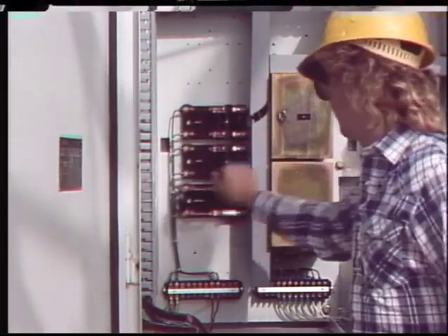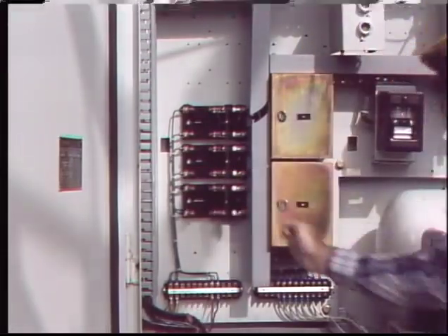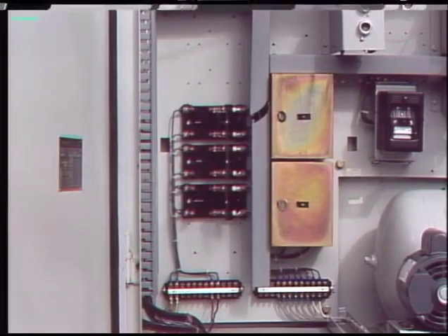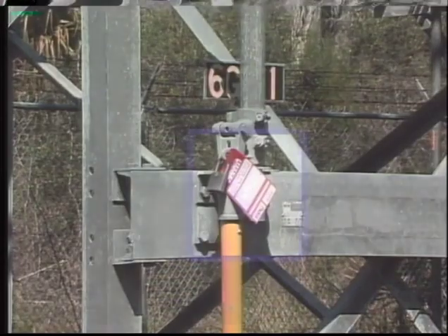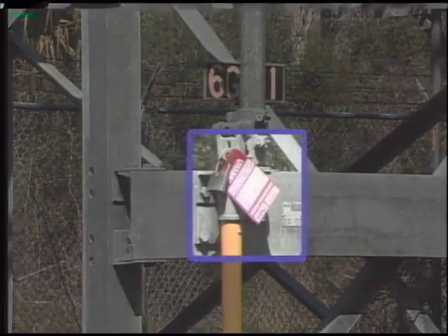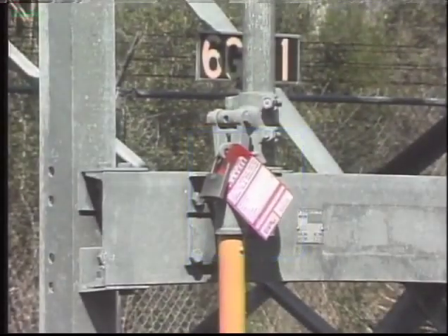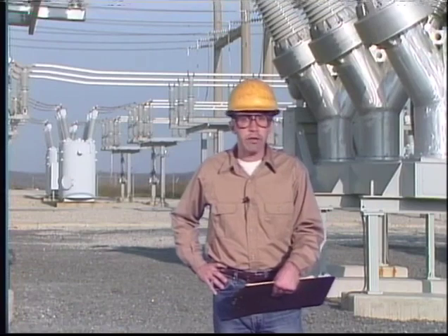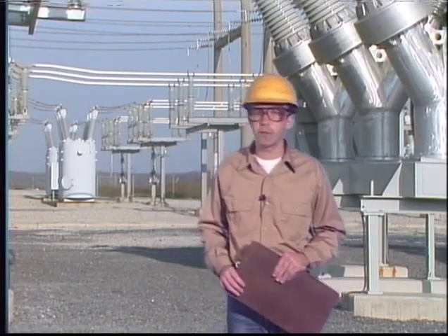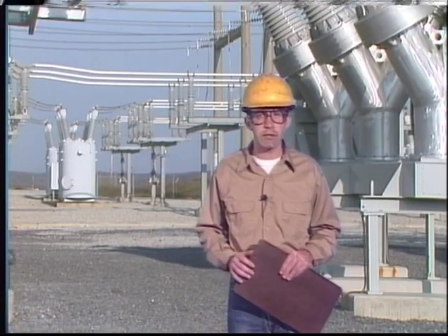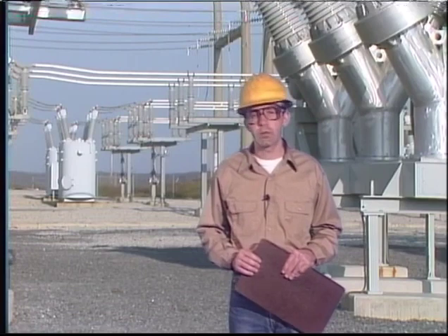Control circuits provide power for trip coils, closing coils, heaters, and other electrical devices in the breaker control cabinet. All appropriate switches and circuits are tagged according to company policies to warn others not to operate the equipment. After a breaker has been de-energized, isolated, and grounded, its control circuits have been de-energized, and all appropriate switches and circuits have been tagged, the breaker is electrically safe to work on.